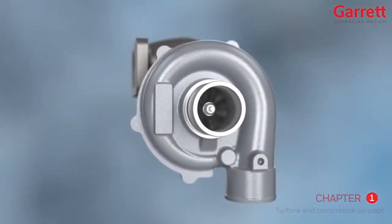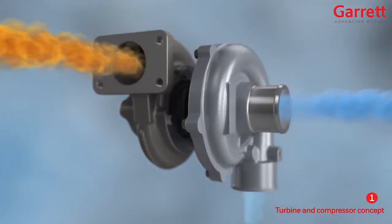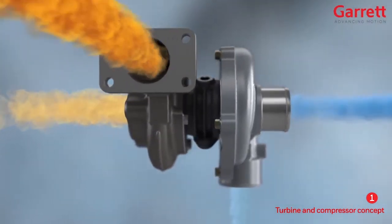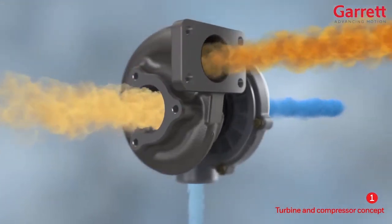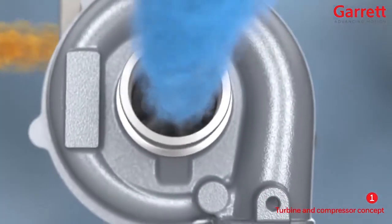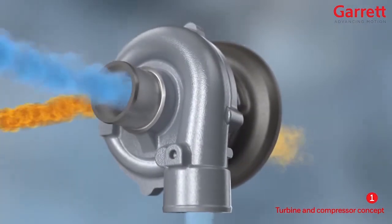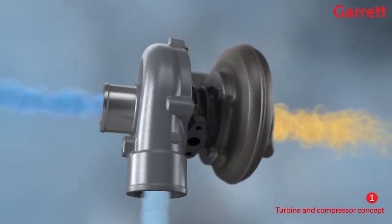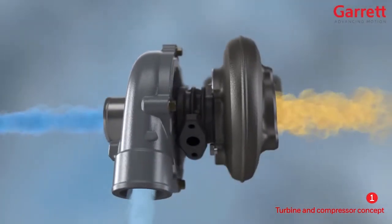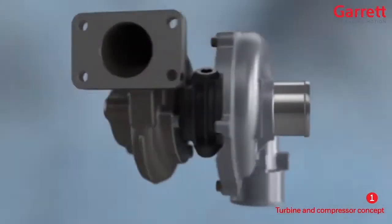What is a turbocharger? A turbocharger is an air pump which supplies air for the engine combustion process at higher pressure and density than ambient air. The turbocharger air contains a higher concentration of oxygen, allowing greatly improved combustion for more power, cleaner emissions, improved engine torque output, and reduces the pumping losses within the engine, offering all-around better performance.